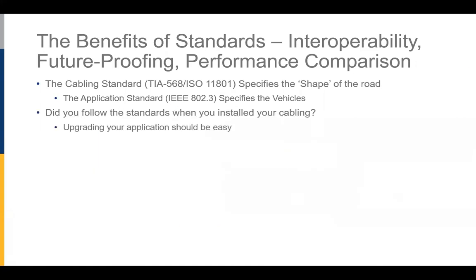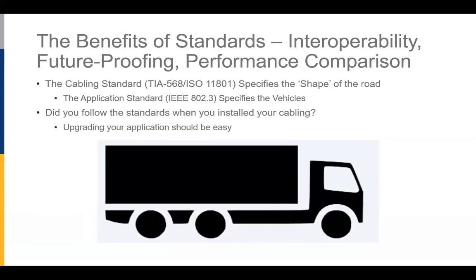Now, if we followed the standards when we were installing our cabling, we punched down 4 pairs, we only went 100 meters, when the next device comes out, when the better access point, when the better camera, when the better card reader, when the better access control method comes out, we can just switch it out on the end and use the existing cabling, saving us a lot of time and effort in our upgrades.